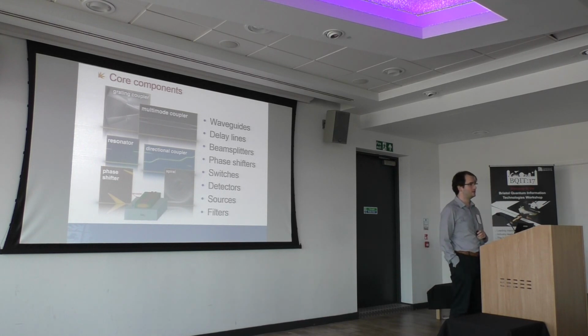the silicon. And silicon has quite a large thermo-optic coefficient, so this allows us to enact phase shifts, albeit at a slow rate. We also have active phase shifters that use carrier effects and dopants in silicon to enact fast phase shifts. So detectors, that's essentially what this talk is about. And finally, we have things like sources and filters that we heard mentioned before in the context of these ring resonators here, where through nonlinear effects, we can generate single photons and things like that.